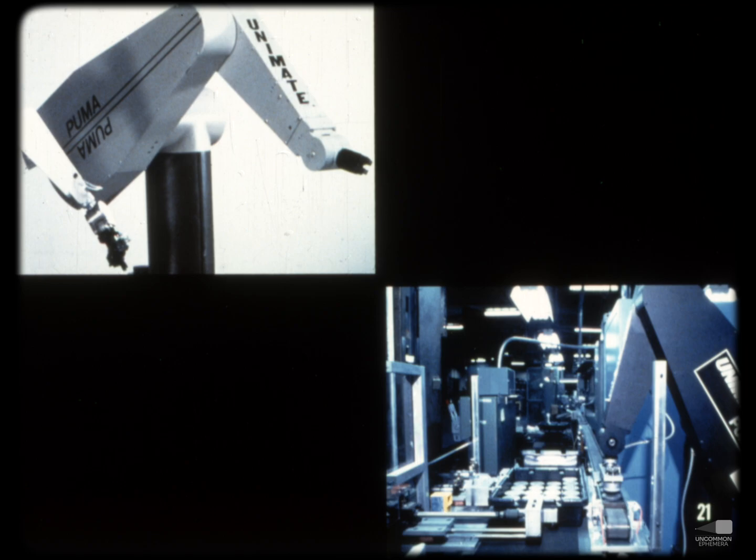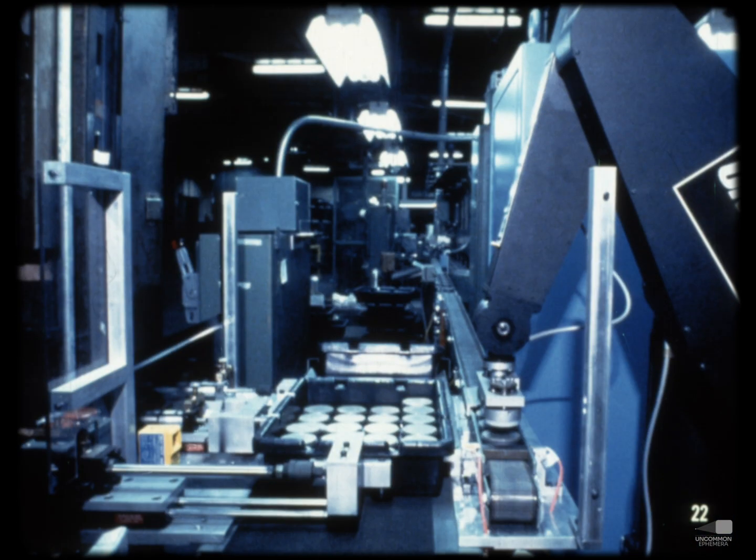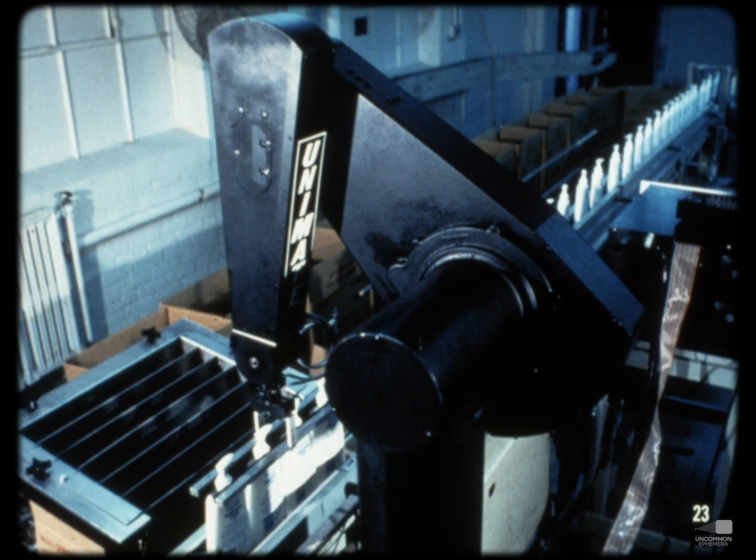The Unimation Puma 250, 500, and 600 series robots are high-technology robots which make use of 5 to 6 degrees of freedom, excluding the motions which may also be available in the gripper. This Puma 600 robot has 6 axes in its arm. This robot is called a jointed spherical coordinate robot because its working envelope is almost a complete sphere. The dimensions of the Puma 600 series robot arm closely approximate those of the human arm.